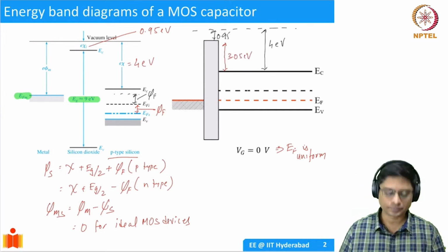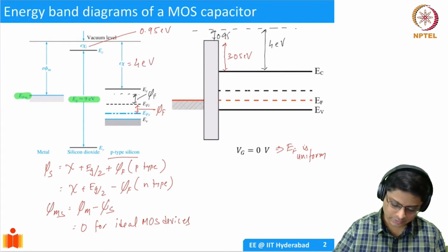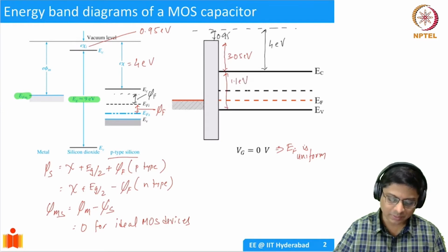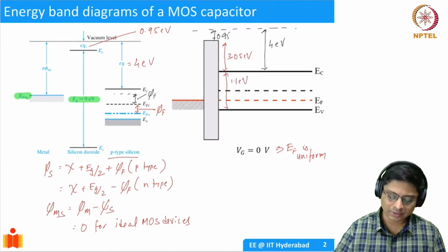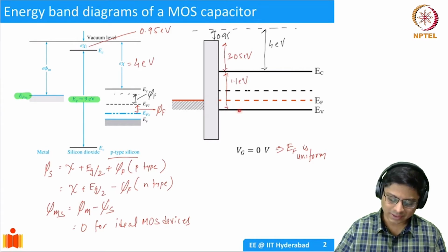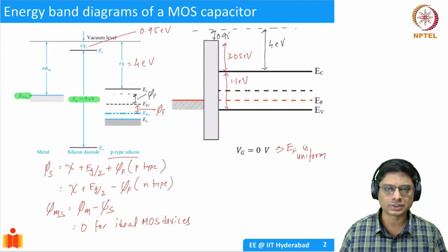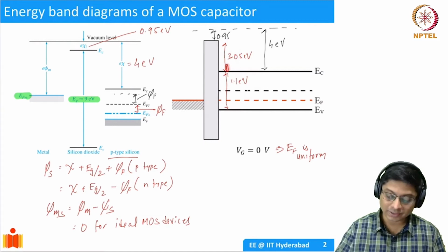Okay. And this is the energy band gap. This is 1.1 EV. Just please remember, these diagrams are not drawn to scale. If I were to draw to scale, then this region has to be 1.1. So this has to be 3 times this. So I'm not drawing to the scale. Okay, just indicate if these are our distances. But you need to remember that this barrier is 3 times almost, slightly less than 3 times the energy band gap. Okay, so it's quite large barrier.